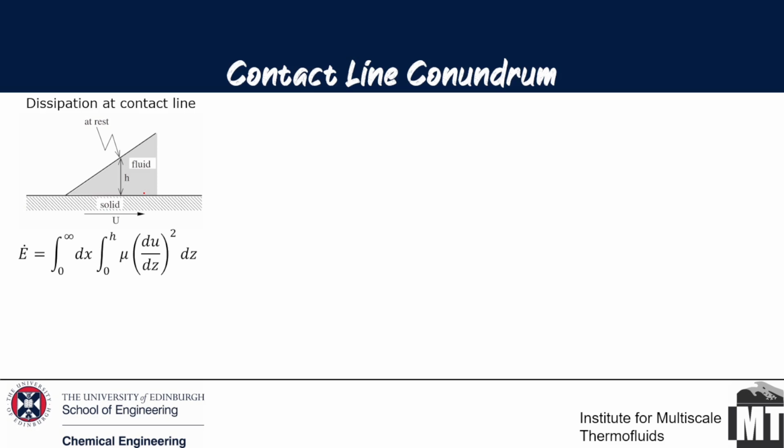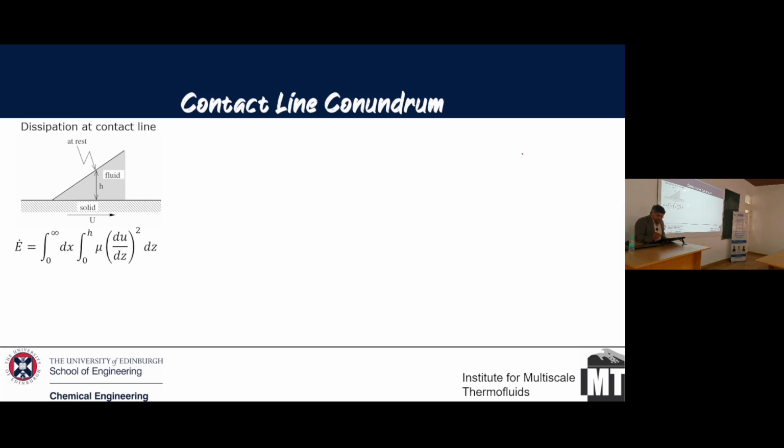Experimental microfluidics, they try to determine the slip length? Yes, they do determine the slip length based on the surface. But again, it's so dependent upon the surface structure. So what people typically do is take the slip length from experiments and put that in the Navier slip condition, because the experiment showed that this is a slip length somewhat. Which is somewhat okay, but it cannot be a generalized thing. It cannot be.